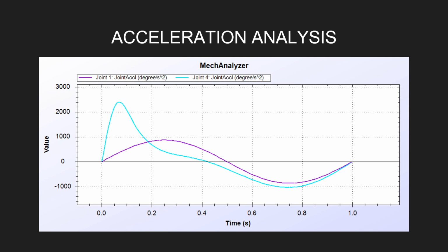Unlike the previous velocity graph, where we can just slide from right to left or left to right in order to analyze the different velocity profiles of opening and closing motion, the acceleration profile for the opening and closing motion needs to be inverted with respect to the y-axis.